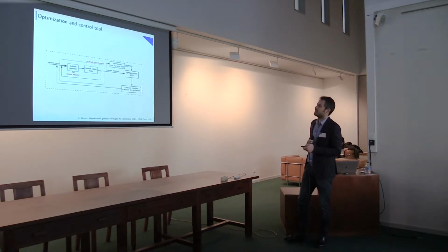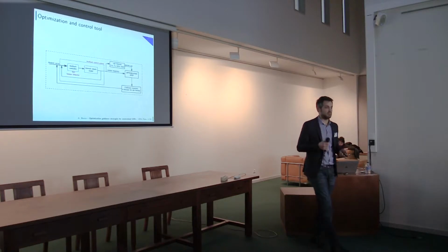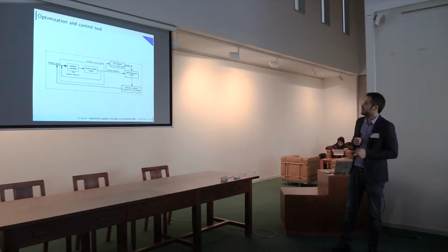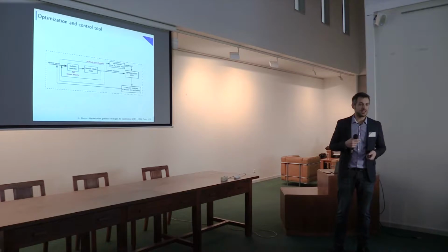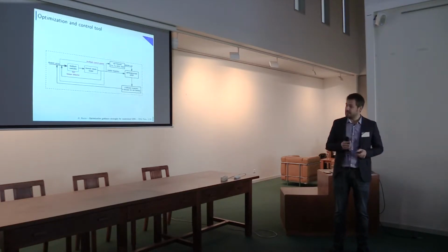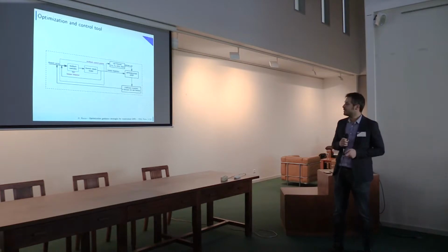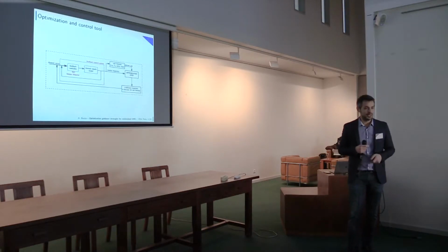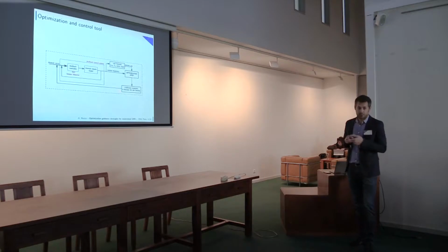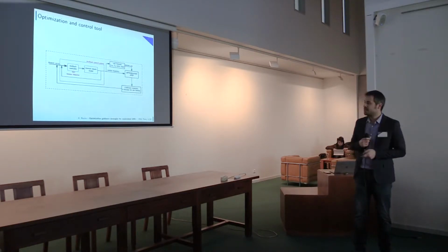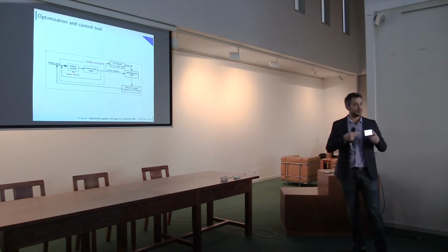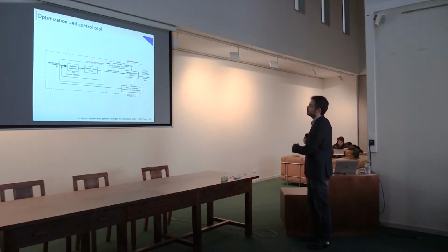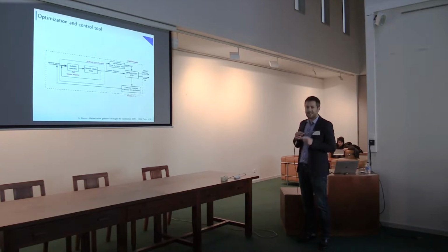Now we can evaluate our cost function, which can be a least squares cost function, or we want to minimize the time. We have the current cost. What we can do is perform some optimization steps. We look for a descent direction in order to decrease the cost function. Then we can do backtracking line search: how far we have to go in order to decrease the cost function. Here we have a curve that does not satisfy the dynamics of our system. What we can do now is project the curve into the manifold of our vehicle. This is actually the main idea of the PRONTO toolkit.